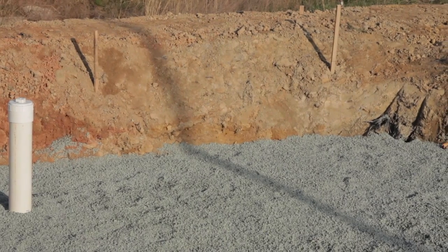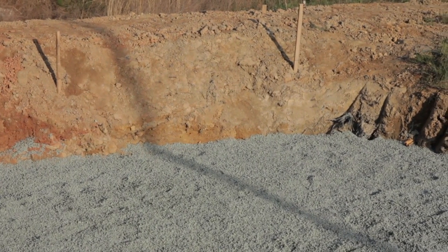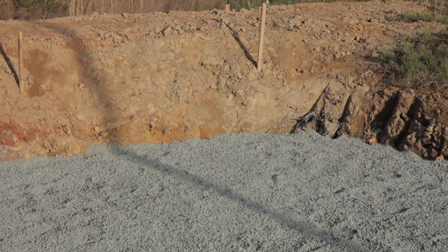57 stone is normally washed before it even arrives at site. The pea gravel is a little bit different because it's a finer stone. It's a number 8 stone. So when you get that on site, you need to make sure that that's been washed, because what you don't want to put in any layer is anything that has any kind of fines or any kind of silt to it at all. Once you do that, then you run the risk of contaminating the filtering layers on any subsequent layers lower.